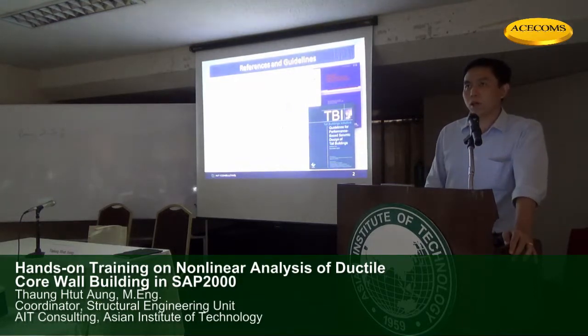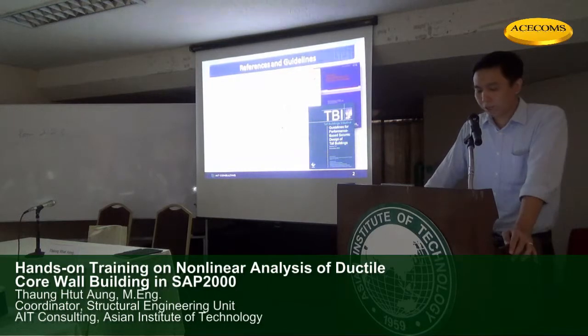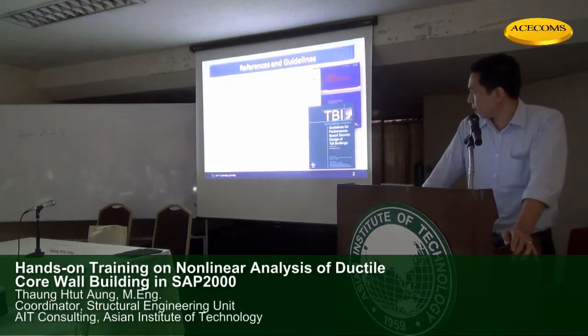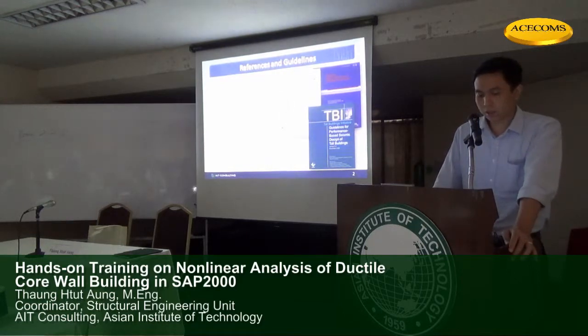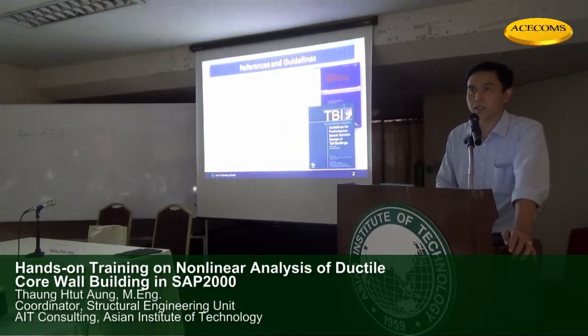That one is the modeling, detailed modeling procedures and acceptance criteria for the performance-based design. Together with those documents, we use the ASCE 41-06 document, which is seismic rehabilitation of existing buildings. It is updated in supplement number 1. Some of the tables are updated, but this document can be used not only for existing buildings, we also use it for new buildings. Now this document is going to be updated with a 2013 version, but it is only in draft version.